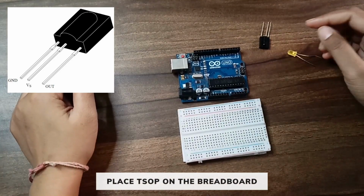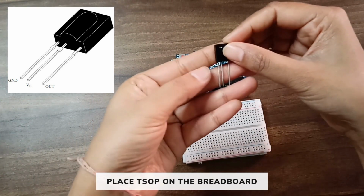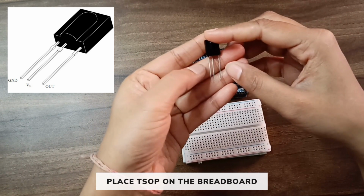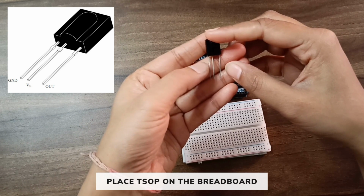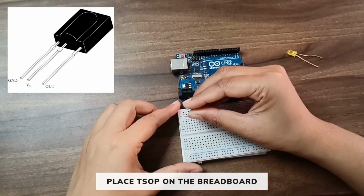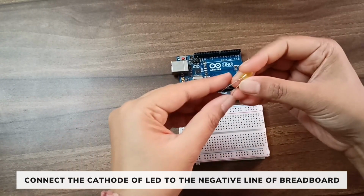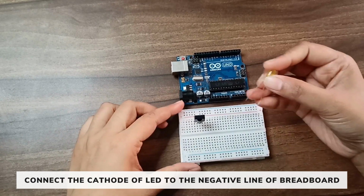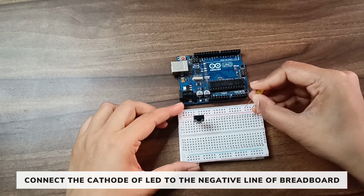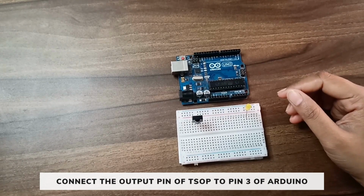First we will place the TSOP on the breadboard. So this is the TSOP IR sensor. It has 3 pins. This is the output pin, the middle is the VCC, and this side on the left is the ground pin. So place the TSOP on the breadboard, then take an LED and connect the cathode to the negative line of the breadboard in this way.